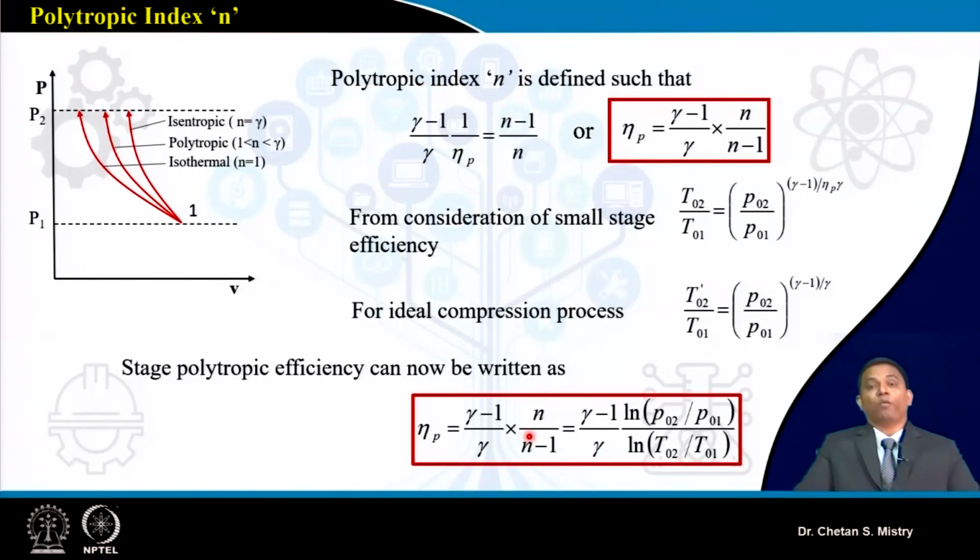So what have we discussed today? We talked about our compression process as a thermodynamic process, and we represented all stages, at the entry and exit of our stage or number of stages, in an overall sense on a TS diagram. Then we understood what is happening in the rotor and stator on the TS diagram. Then we discussed adiabatic efficiency and what we mean by polytropic efficiency.